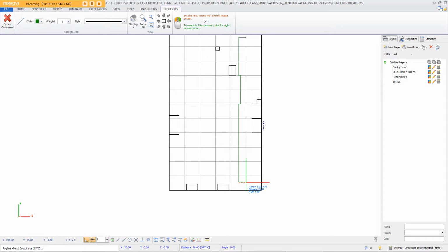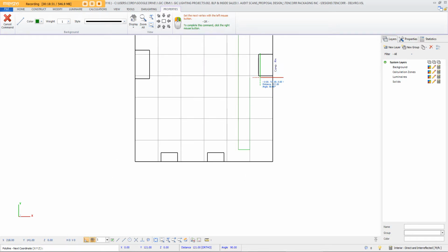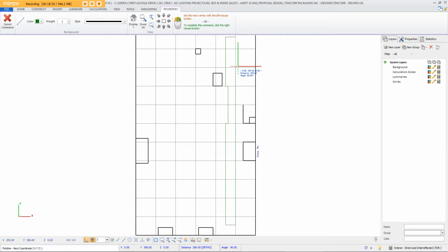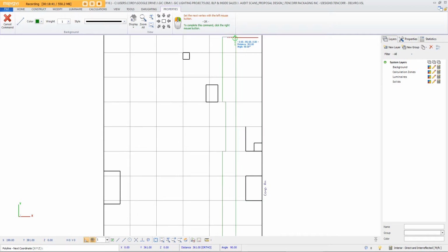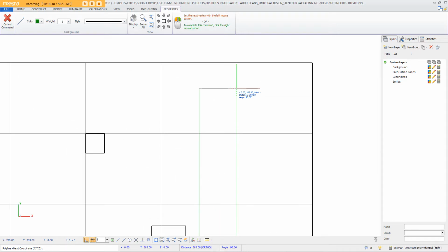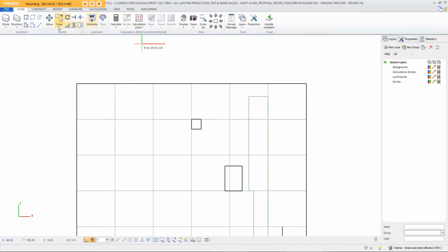So we're going to just go back to this line here, and it's going to go all the way up. Now instead of going all the way up, I can just close this off. Oh no, sorry, this is a line function. So I actually have to go back and close it off. If it was a room function, then you could just right click and the last point will automatically go to the initial point, whether it's straight, on an angle, however it's located. But this being a line, we actually have to close it off. Okay. There we go. So that's closed off.